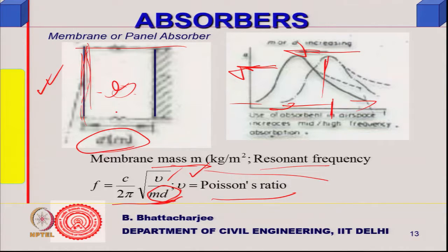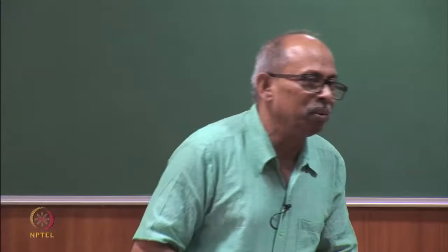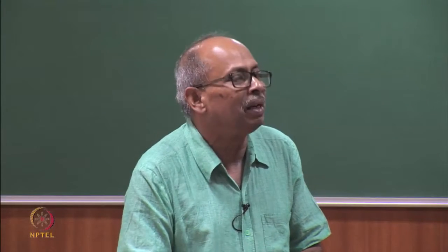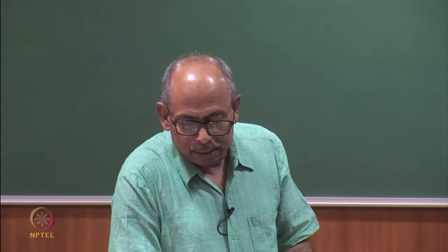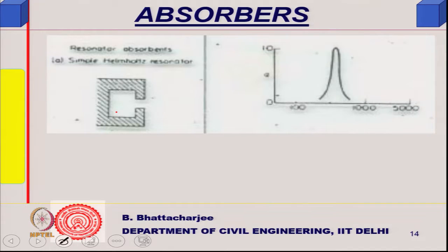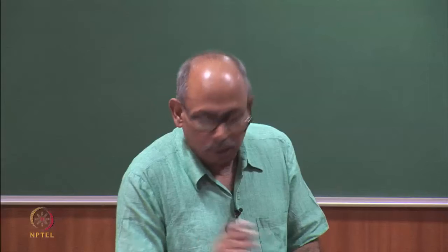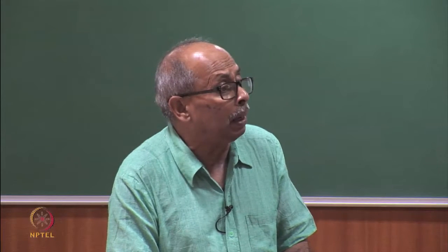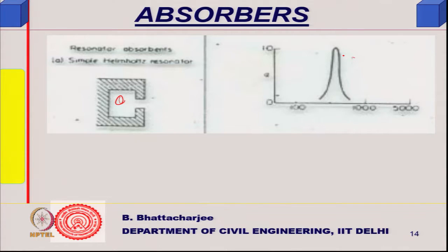So, I do not mind some resonance there, because I am not going to put someone inside that distance, this distance is relatively small. Similarly, this Helmholtz resonator will actually resonate within this, right, but nothing will happen outside. So, a very specific frequency, very narrow band, but actually 100% absorption at a narrow band frequency.